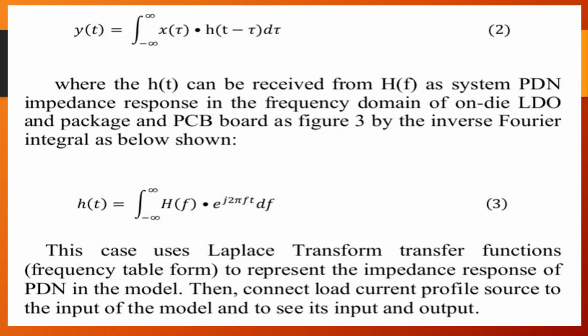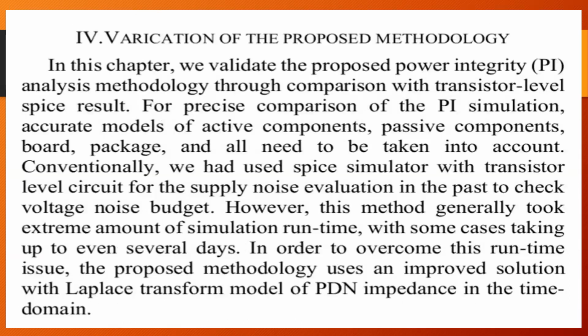h of t equals the integral from minus infinity to infinity of capital H of f times e to the power j 2 pi f t df. This case uses Laplace transform function to represent the impedance response of PDN in the model. Then connect the load current profile source to the input of the model and observe its input and output.